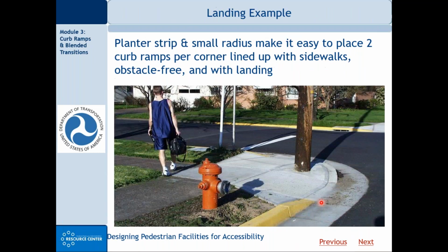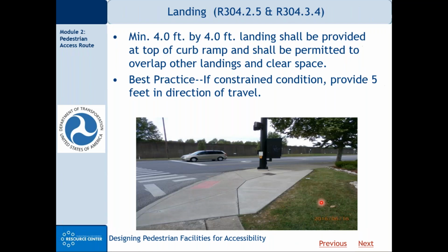Ron, we have another question for you. Okay. This person says many standard drawings in Ohio call out the gutter cross slope as 1 by 12 or 8.33%, or 1/12, sorry about that. Does this mean the ramp could only be 5% max?